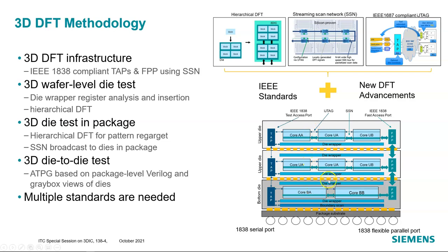Regarding the die-to-die tests, we have to consider stuck-at and SB tests, and sometimes high-speed I/O SerDes test. Hierarchical DFT provides a die gray-box-based solution for performing die-to-die ATPG for both stuck-at and SB tests. This reduces the computation resources to the very minimum. For the high-speed SerDes test, the I/O-based SSN instrument is usually used and connected to the IEEE network to automate the setup and result viewing in the package.